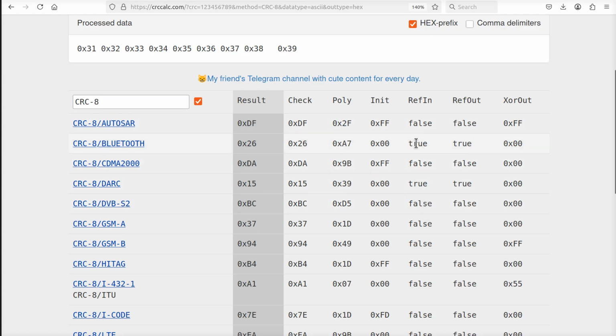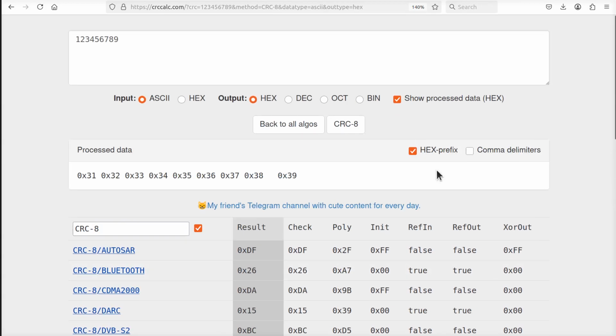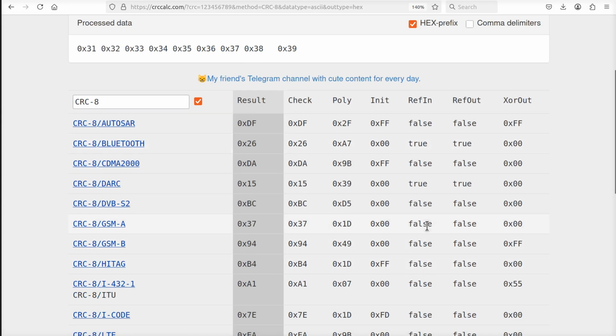Ethernet is big endian bit order, so you're going to want to use one that is. I don't remember off the top of my head if reflected is big endian first or little endian first. I'll have to look and see what my code does to remind myself in the test bench, because I actually have some logic that reverses them in there to make sure that these are correct, okay?